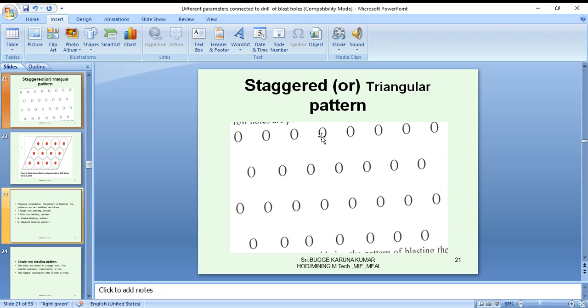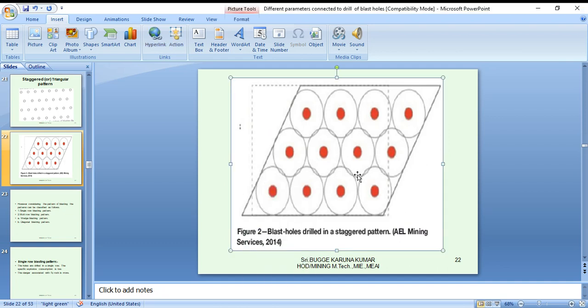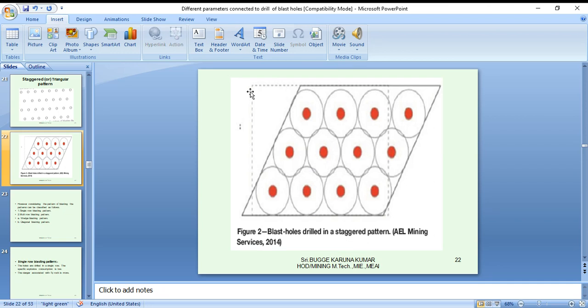Blast hole patterns change. Before drilling, the marking is done in such a way that the blasting in-charge will blast according to the design of the blast. So there is a special advantage over the regular patterns, and also the staggered pattern. One more sketch is shown here, blast drilling in the staggered pattern. You see here that half of the material is staggered from the main row.